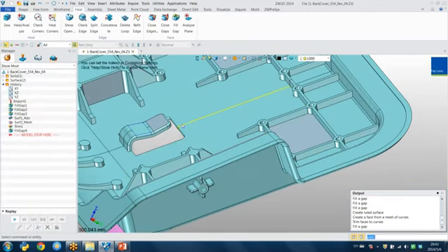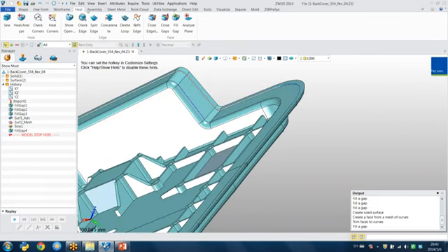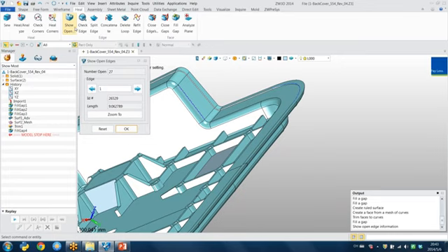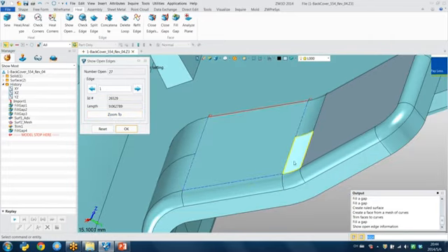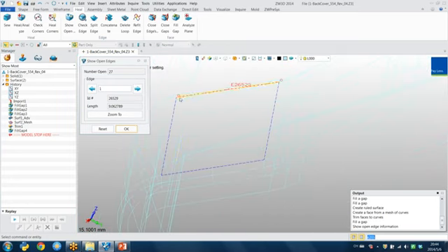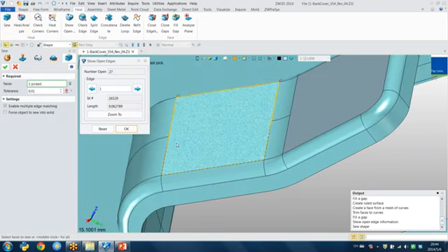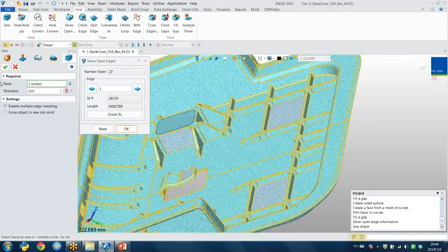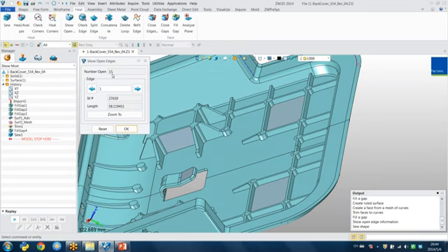So after that, you can use open edge here, and they still have 27 open edges, so zoom to. So you can find this is the open face. You can find if I change them to wireframe, it is more clear. So with this one, you can use sew. Okay, you can select the wall and press OK. So then you can find they still have 15 open edges.